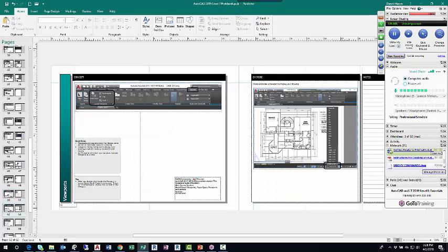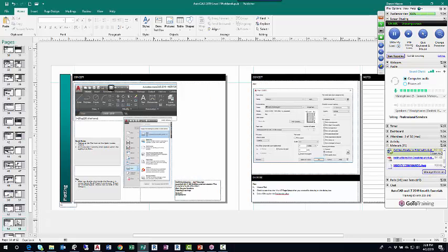Then on page 52 and 53, we have your viewport configuration, how you use the rectangular button to create the viewport, open the viewport, and scale it to whatever fit, and we kind of hunted and pecked, but it came out to 3/16. And then finally, page 54 is plotting.